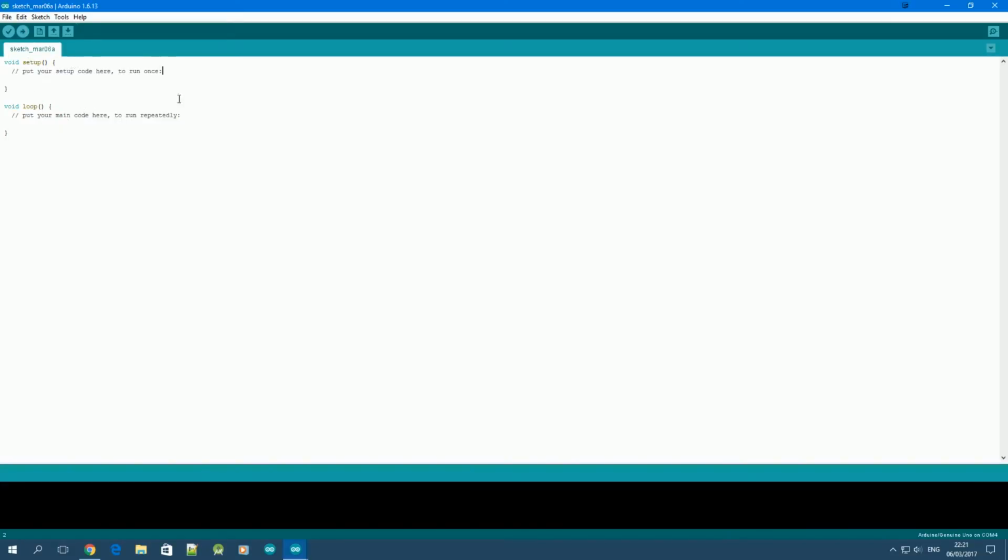After the setup function runs, the next bit of code that runs is found in the loop function. The loop function, again, as the name suggests, contains code that runs indefinitely. Think of it as code that runs all the time while the microcontroller is running. This is essentially the function in which you'd put the meat of your code and program that you want to run on the microcontroller.